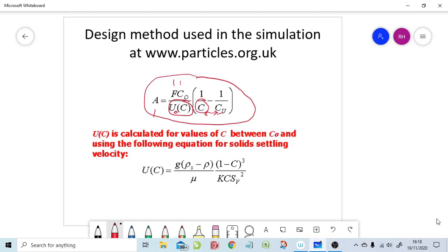So clearly we need an equation for U0 as a function of C. And in the previous video, the old technique for solving it was given, and that is based on the Kozeny-Kármán equation, because what we have just here is permeability according to Kozeny-Kármán. Okay, Kozeny-Kármán is a well-known equation, well-known permeability expression.